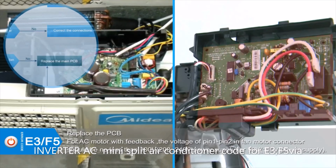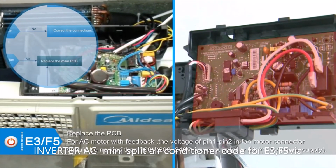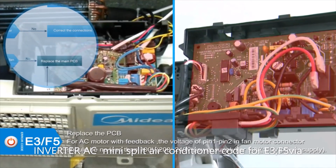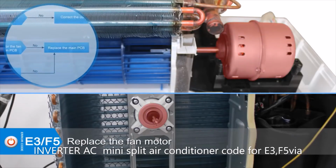If the value of the voltage is lower than 100 volts, 208 to 240 volts power supply, or 50 volts, 115 volts power supply, the PCB must have problems and needs to be replaced. If the value of the voltage is normal, the fan motor needs to be replaced. If the error still exists, replace the main PCB.